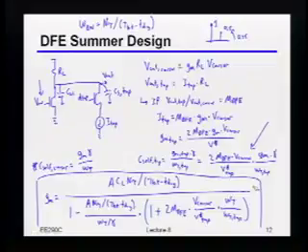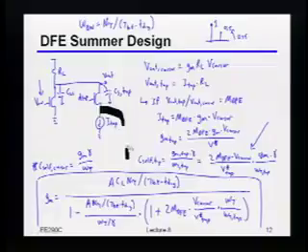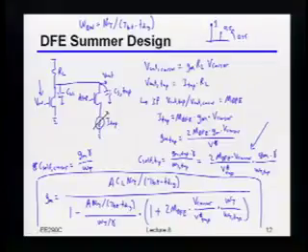That's a great question. It turns out that, for exactly the reason you're asking about, even though I've said that this thing is hard switched, you tend to actually want to keep it in saturation. Because indeed, you're right, you'll pick up all of the parasitic cap from that tail current source right there. And this is obviously a digitally controlled thing, let's say about a 6 or 7-bit DAC. There might actually be a lot of parasitic cap on that node.